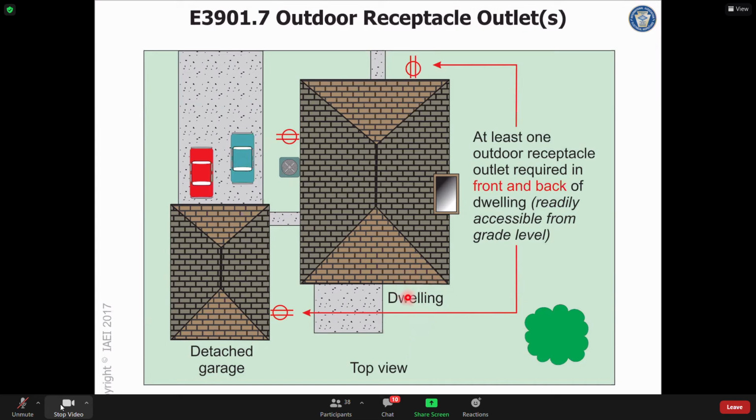Don't we also have rules that say we have to have a receptacle located within 25 feet of each HVAC type equipment? So what if I had my condenser, AC unit, sitting right here, and I had my required receptacle right beside it? Would that receptacle be able to kill 2 birds with 1 stone? Yes.